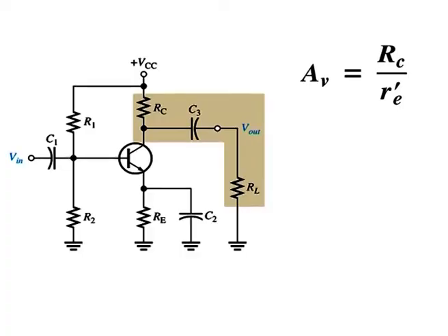Stability of the voltage gain. Stability is a measure of how well an amplifier maintains its design values over changes in temperature or for a transistor with a different beta. Although bypassing Re does produce the maximum voltage gain, there is a stability problem because the AC voltage gain is dependent on the AC emitter resistance, that is r'e. Also, AC emitter resistance depends on Ie and on temperature.